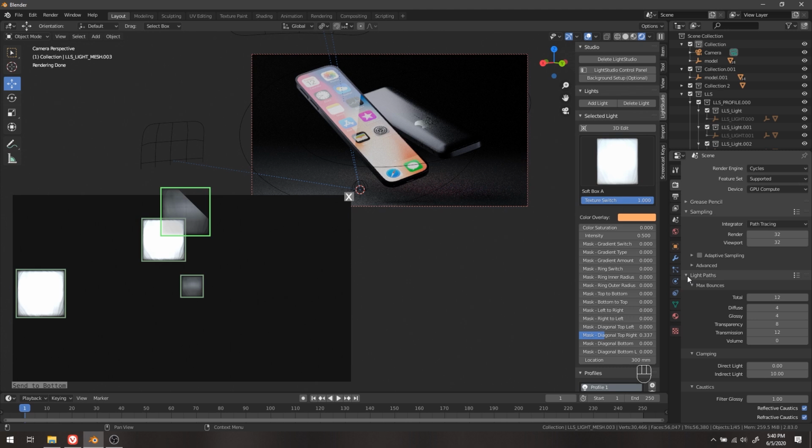We're going to extend this lighting panel and then set it to limited global illumination. That's just going to reduce the number of bounces the light is taking. Again, something I can explain in depth in the future. Just take my word for it for this one.